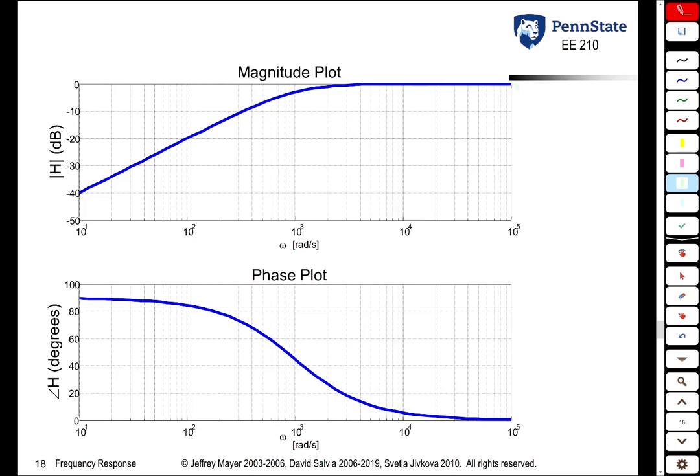So if you were to plot the magnitude and phase plots here, you would see now that for high frequencies, we get a gain of approximately 1. For low frequencies, we get gains much less than 1. And once again, where is the break point? It is once again at 1,000 radians per second, or 1 over RC.